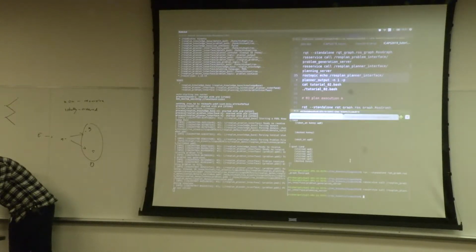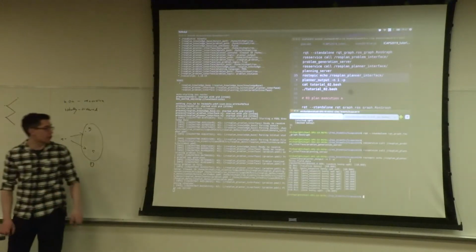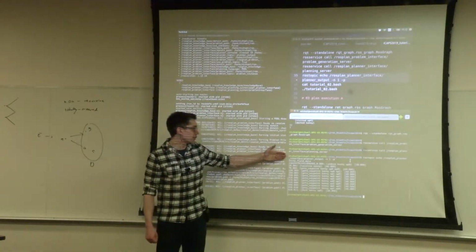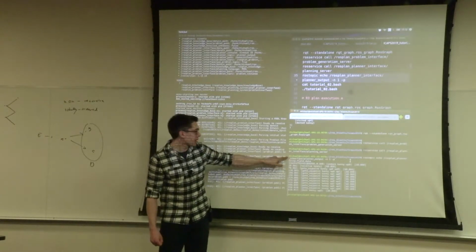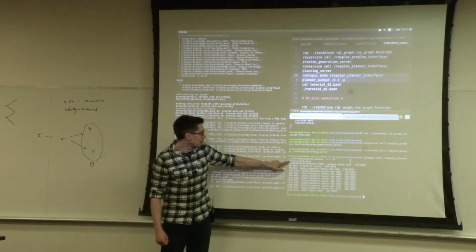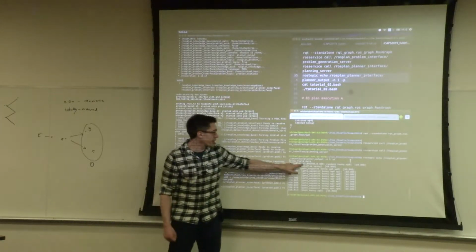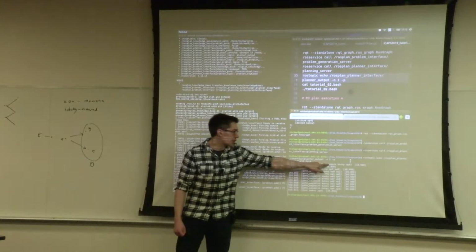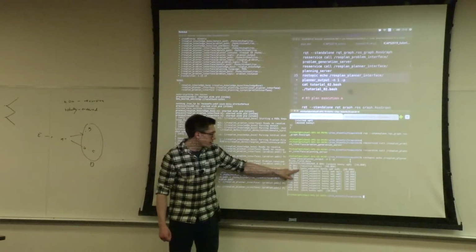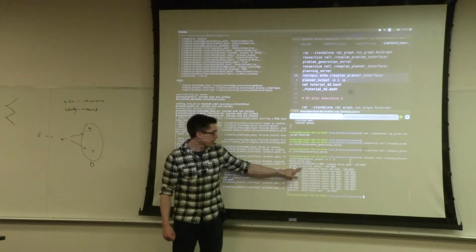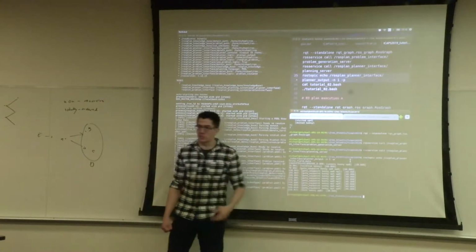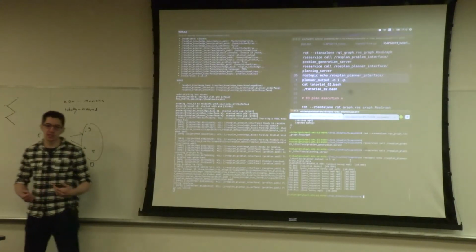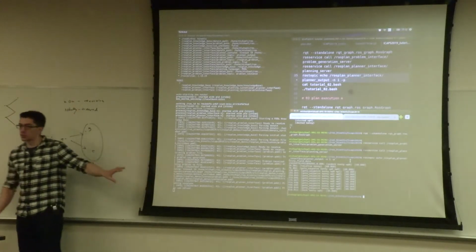And I can publish the planner output topic. So again, this is just echoing the last message that was sent on this topic, ROSPlan planner interface planner output. We have the time and field.data, so this is the timestamp of the message, that's just a ROS thing. And then from this point on is the plan. So at time 0, undock, localize, go to a lot of waypoints, and dock. For some reason it's revisiting waypoint 0 after visiting any other waypoint, but I did mention I didn't do any optimization. This was just the first plan that was found by POPF.